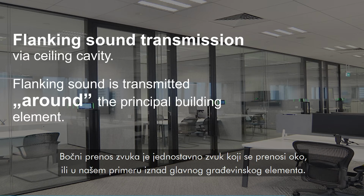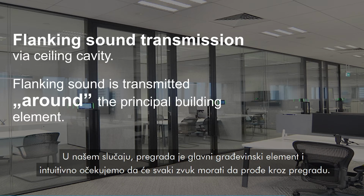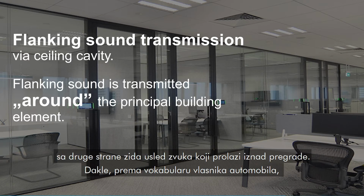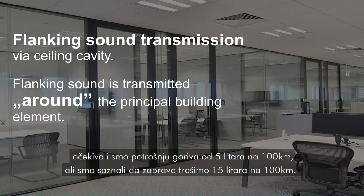Flanking sound is nothing more than the sound which is transmitted around the principal building element. In our case, the partition between two offices is the principal building element, and of course we are intuitively expecting that all the sound will pass through this partition. However, in real life we end up very surprised when we figure out that we can clearly understand the colleagues on the other side of the wall because the sound is passing above the partition. So in the car owner's vocabulary, we were expecting a fuel consumption of 5 liters per 100 kilometers, and now we found out that we actually consume 15 liters per 100 kilometers.